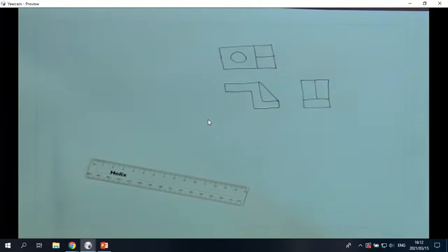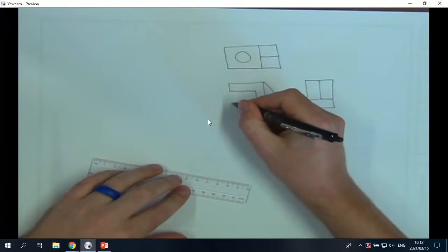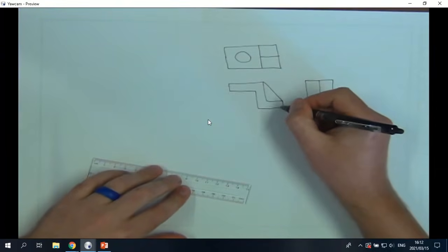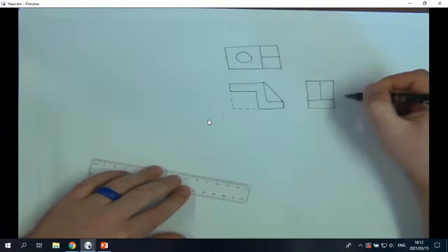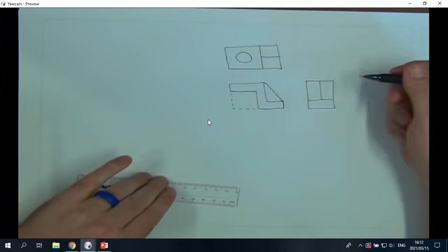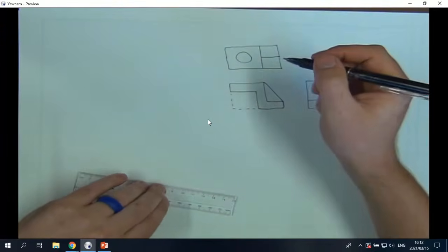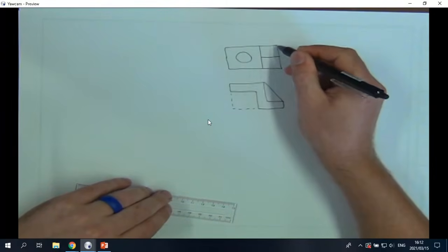Now we want to make an isometric view of that. About the 30 degrees, yes, you just eyeball it. This one is 6 blocks long and 4 blocks high. The right-hand view is 4 blocks wide, 4 blocks high. Not that it looks like it in my view, but I'll draw the isometric in correct proportion. The top view would be 6 long, 4 wide.